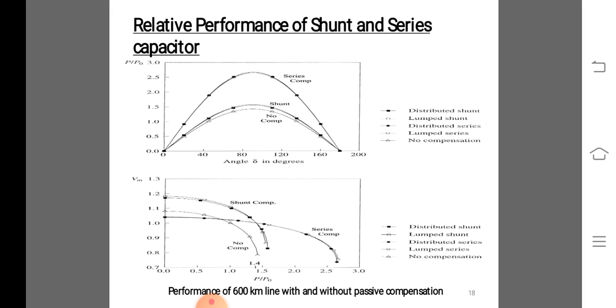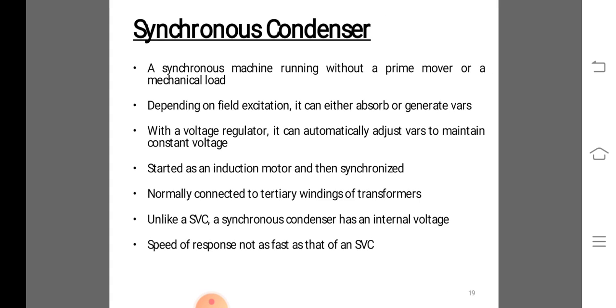Commutation from capacitor to reactor and vice versa should be fast. No switching of the capacitor at the high voltage busbar, so that no higher frequency transient is produced at EHV level. Elimination of higher harmonics on the secondary side and blocking them from entering the system. In a three-phase system, the thyristor controlled inductors are normally delta connected so as to compensate unbalanced load, and the capacitors may be star or delta connected.